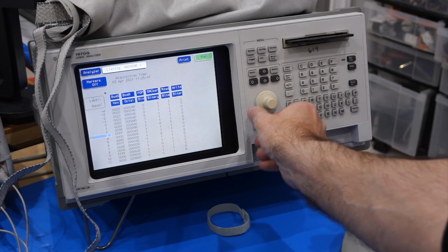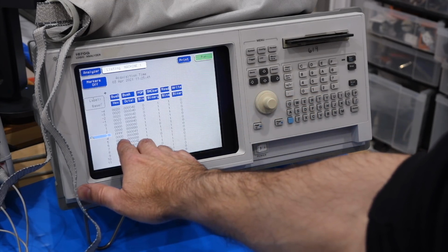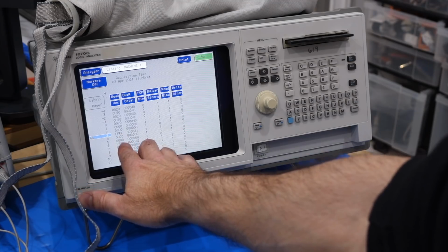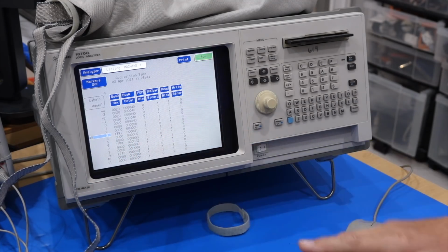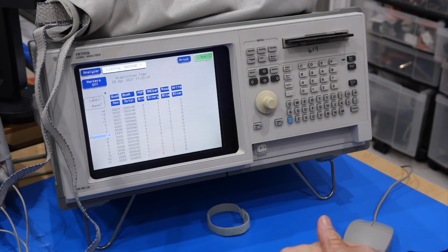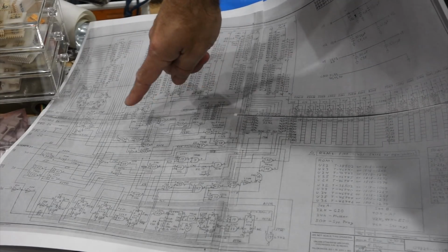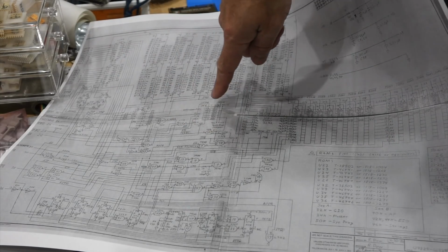Oh, you know what? It's reading FF. Yeah, it's just sequentially getting FF back, getting garbage back from the ROM. Right. So I guess this tells us the processor is trying to work and can't read instructions. It's not getting valid ROM. So you know what else we have to do? We have to look after the latch. So one would think the ROM is dead or something simple like that.